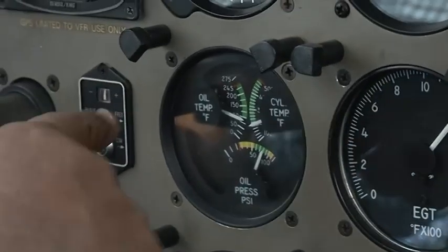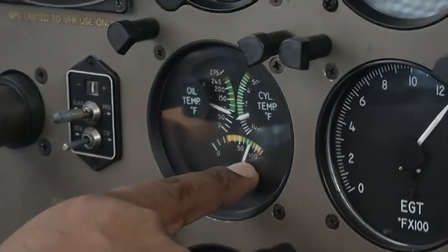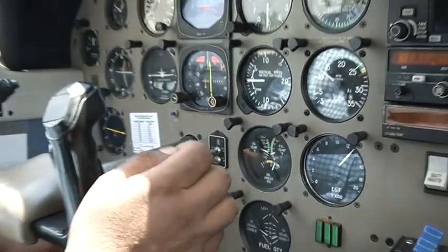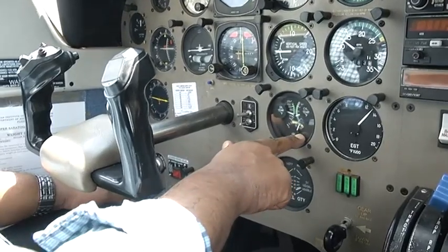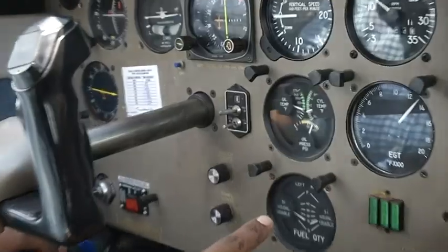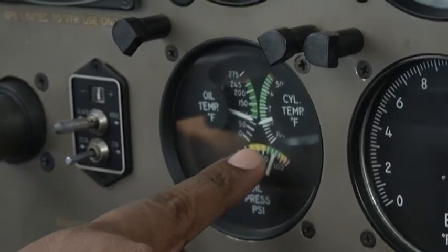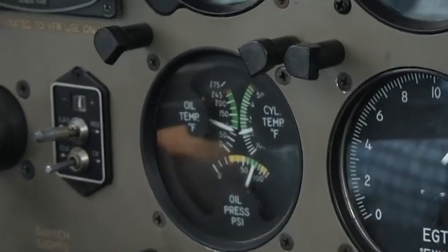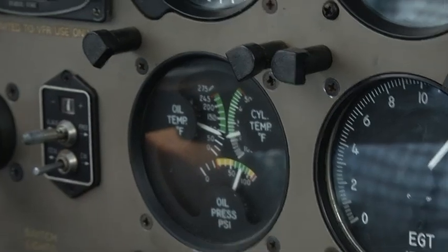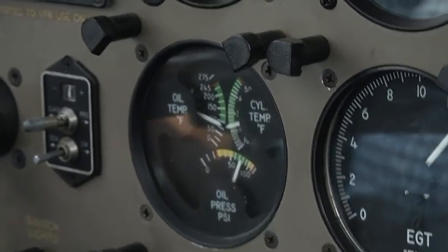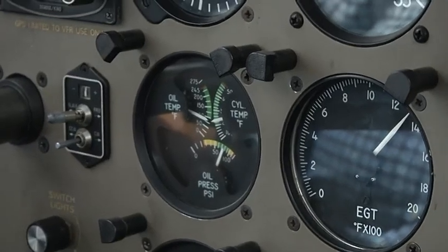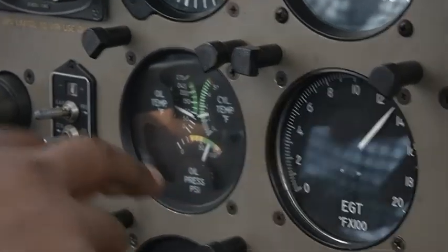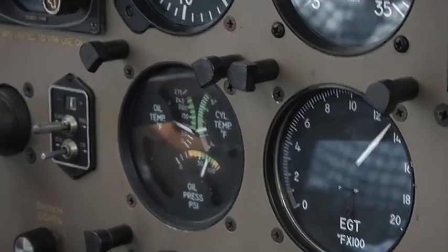As I had told you earlier, this is your temperature gauge and this is your oil pressure gauge. The very first thing you need to observe just after starting is that your oil pressure should register within 30 seconds. As soon as we started, the oil pressure gauge needle has come to the green range, it has registered. In case the oil pressure needle does not register, then you have to switch off the engine. That indicates your oil pressure is nil, that is, your oil has not started circulating in the system. With the oil pressure needle registered, this indicates that your oil is circulating in the system.